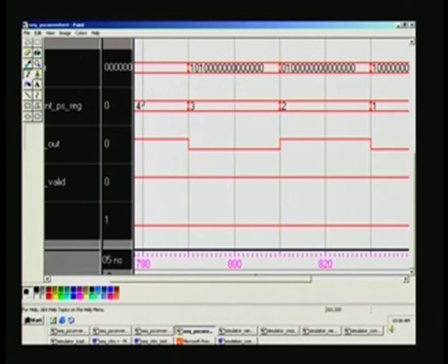So, you can see again it was at 4. So, it is left shift. So, what you have is one must get, now it should shift in this fashion. So, one must get dropped. And one must also go through the output, and this is taking place here, because shift happens here, but it will get reflected only at the positive edge of the next clock. So, and so on it goes.